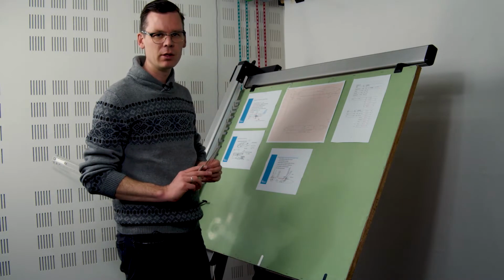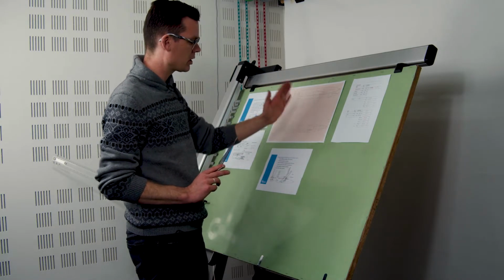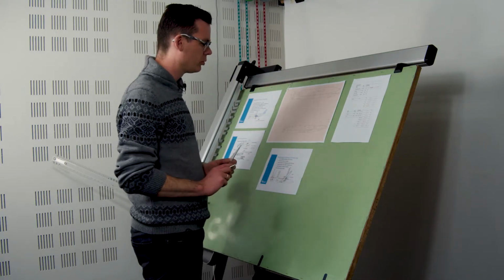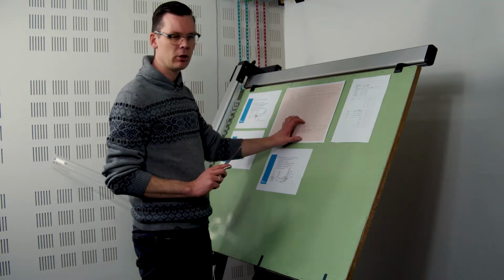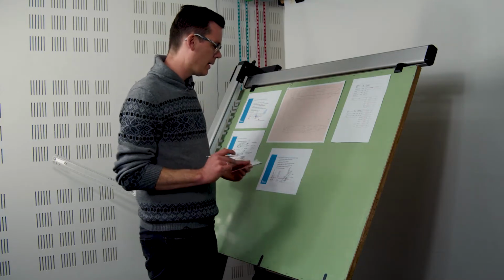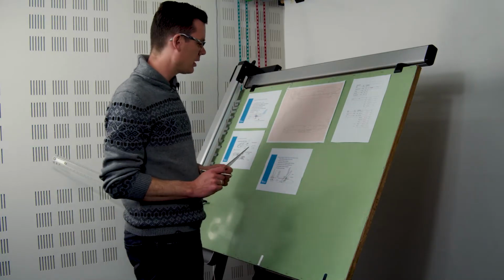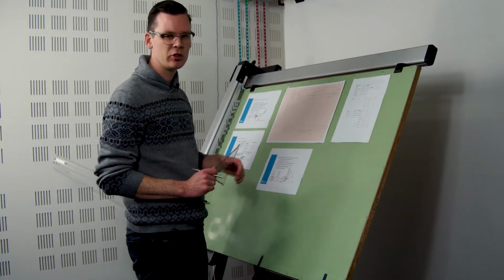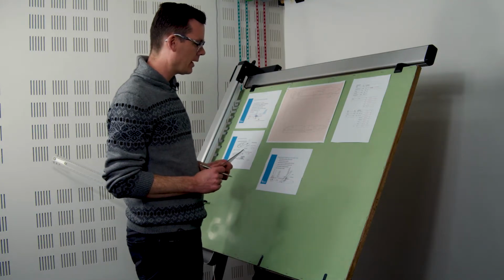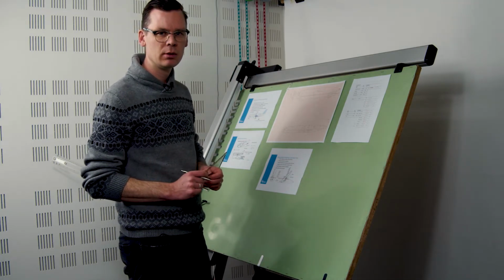define the scrape angle of the fuselage, the maximum angle that it can rotate. That can be a little bit lower than the longitudinal tip over angle, but you can also choose it to be the same. I choose it to be the same for now, which means that the fuselage is preventing this airplane from rotating more than 12 degrees. Then it's actually tipping on the ground. And I have to make sure that happens when the oleo is fully compressed, right?